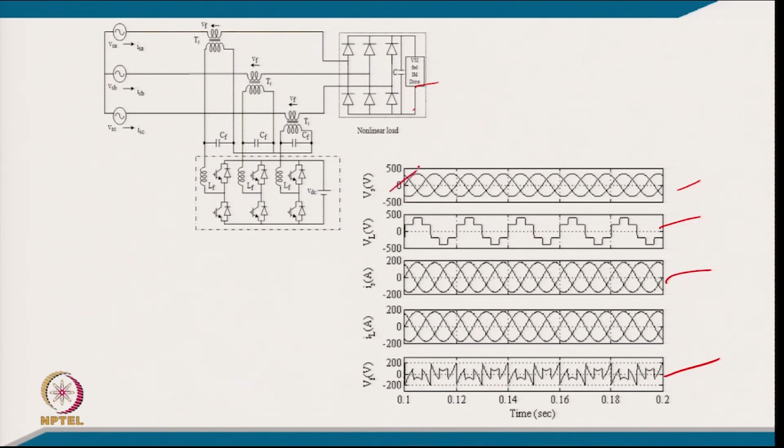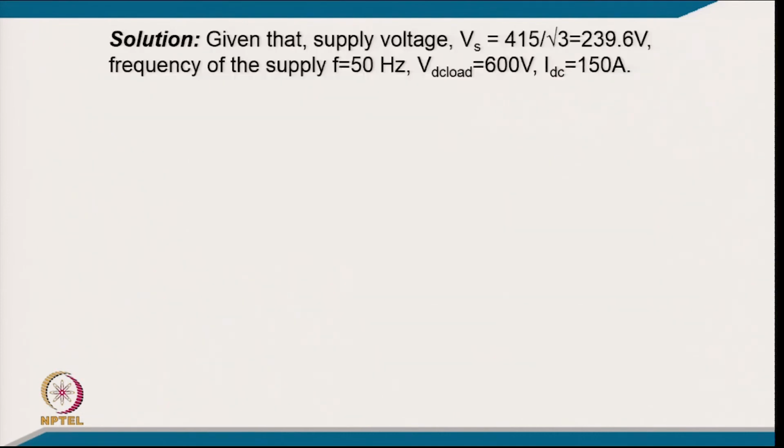So, on the supply we will get a sinusoidal current, balanced, at unity power factor, and this is of course the PCC current, because it is in series. So both currents will be the same. So this series active filter is virtually working to eliminate the current harmonics, not typically eliminating the voltage harmonics, but we are injecting the voltage, and that is in series. So that is why we call it the series active power filter.